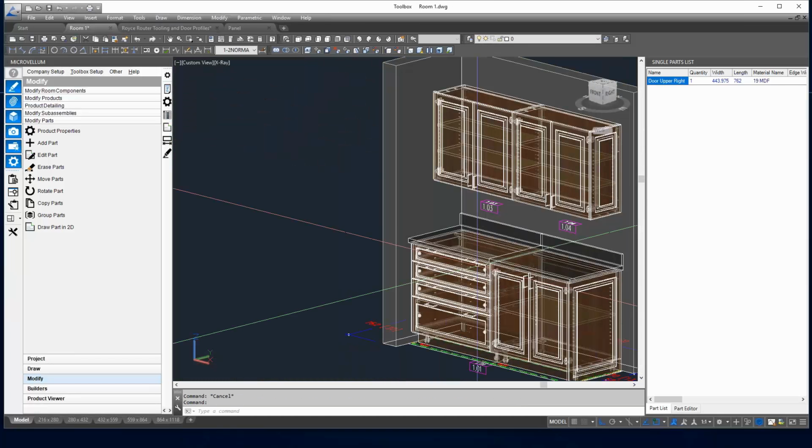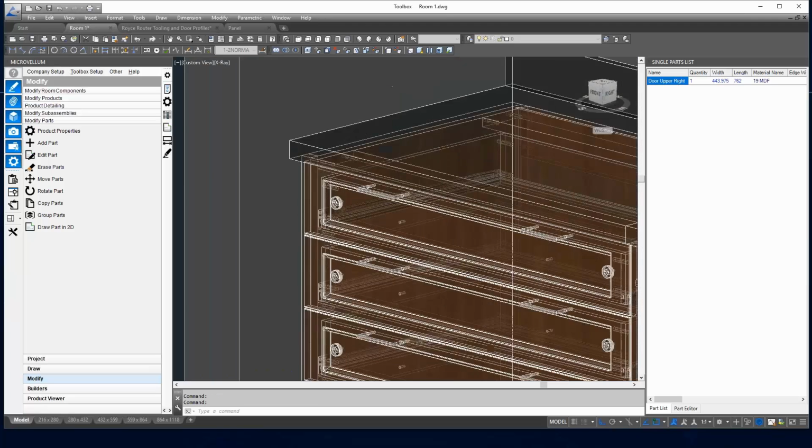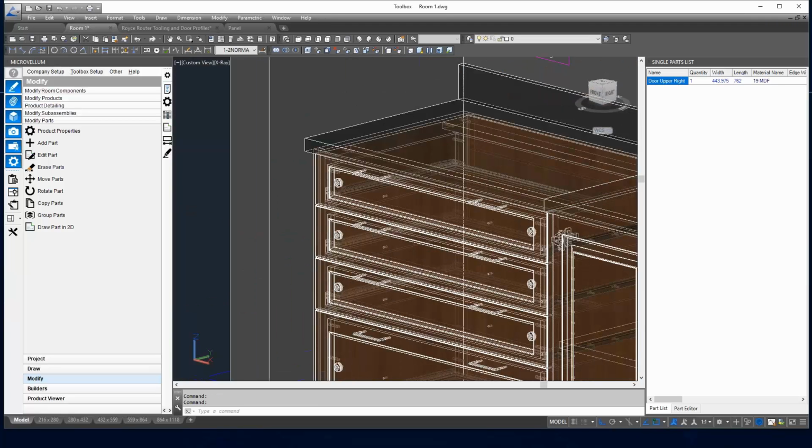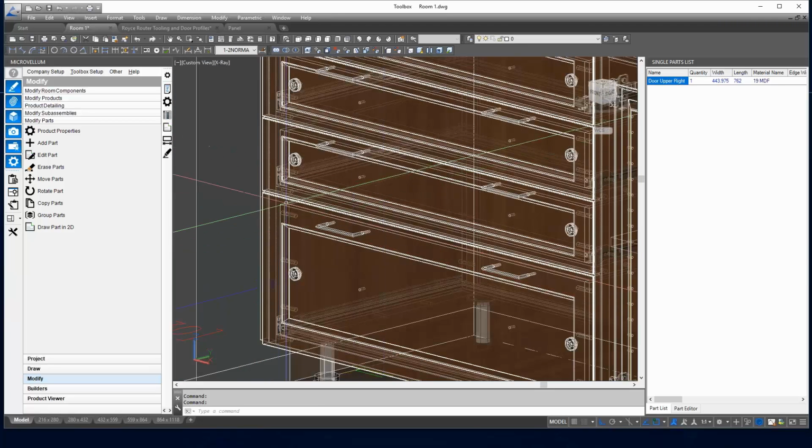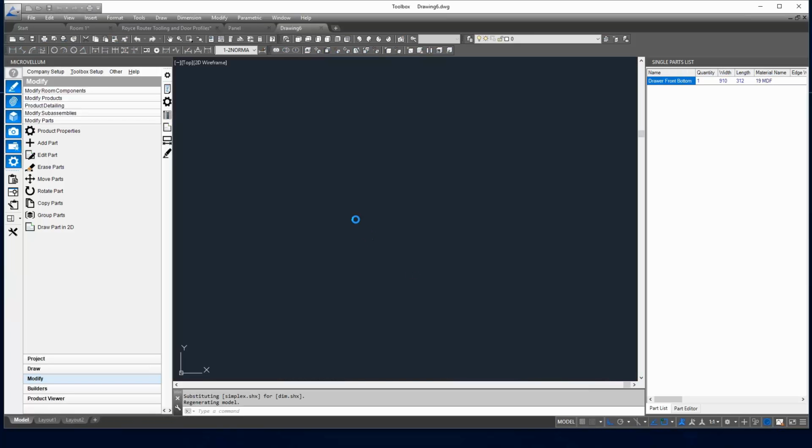If I go over to my drawer fronts here, you can see that I have a flat panel in for those ones. The tool that I set up to do that pocketing was an 1 3/4 tool, so these ones are actually small enough that just a single pass around those is going to take care of that. But on this bottom drawer, I can have a look and see where that machining is going to happen, and so that pocketing tool is going to go and pocket out the outside of my profile, and then also come through and pocket out the center panel option that I have in here to machine all of the excess material away.